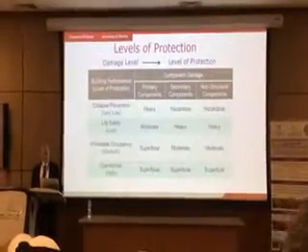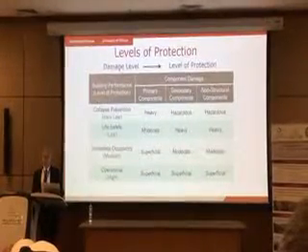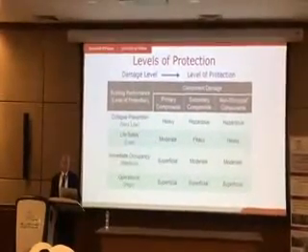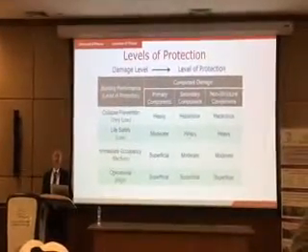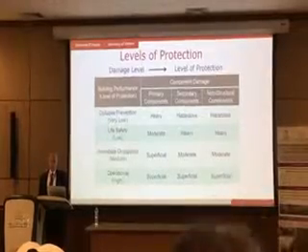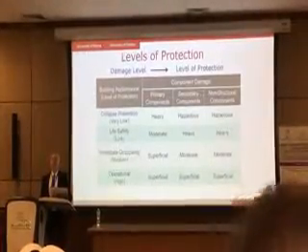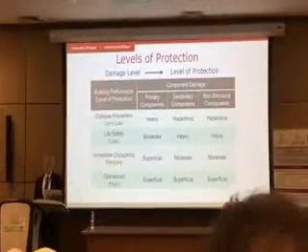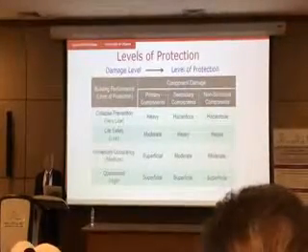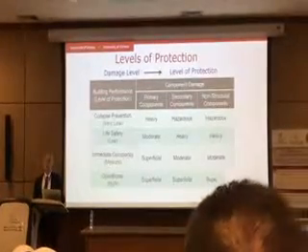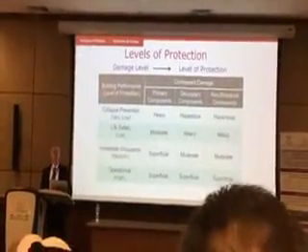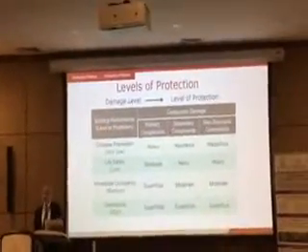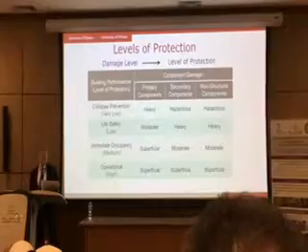Your primary members should be moderate, which means B2. Your displacements have to be less than B2. Your secondary components can be heavy, it could go up to B3, and then non-structural could be heavy as well. So you have to look at those three combinations to decide. And for operational, everything has to be superficial because people need not leave the building. So you essentially apply this to structural and non-structural members.